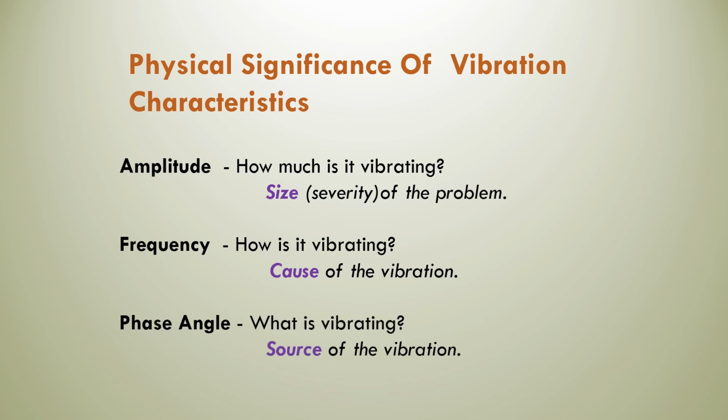Phase angle. Phase angle relationships provide critical information about the spatial distribution of vibrations and can help diagnose the source and propagation of mechanical disturbances. Analyzing phase data enables engineers to pinpoint the locations of faults, identify mode shapes, and optimize structural designs to minimize unwanted vibrations.